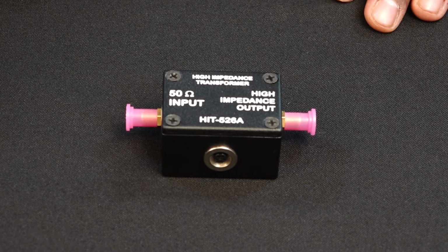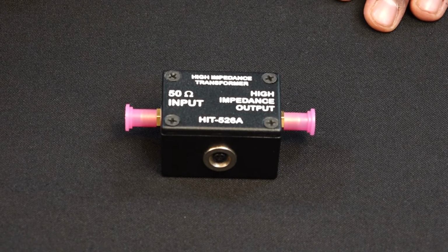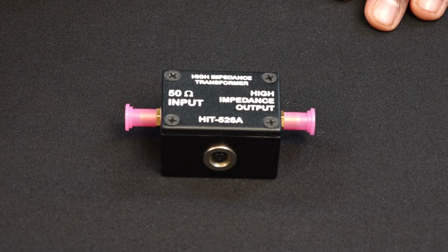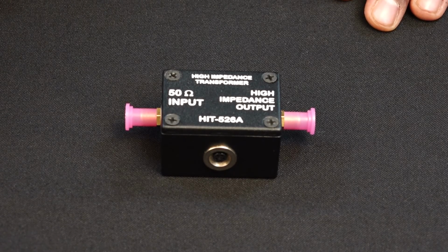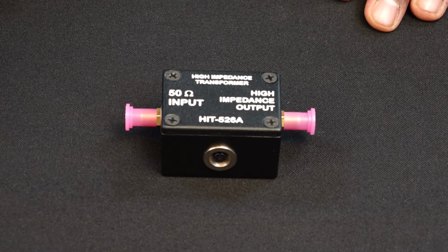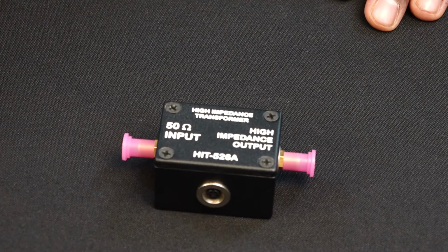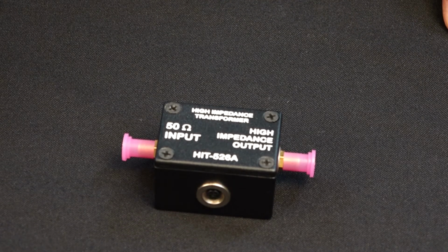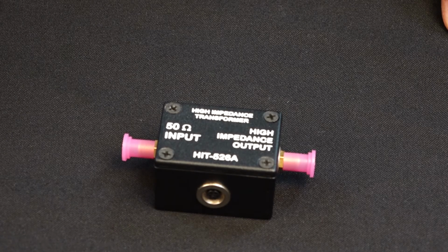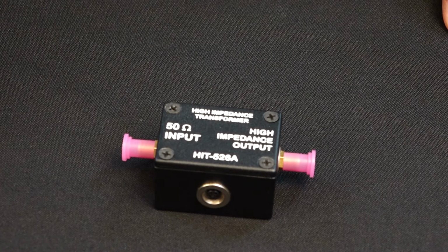The next component that I'm going to show you is called a high impedance transformer. I was telling you that all the transmission lines and all the components that we use have a 50 ohm characteristic impedance. Sometimes you would want the whole TLP setup to have a higher impedance than 50 ohms. In that case, these high impedance transformers come into play. You connect these high impedance transformers immediately after the switch that I've shown you before, and this transformer then switches the impedance of the whole setup from a 50 ohm setup to a 526 ohm setup. So you are then using a TLP transmission setup that has a characteristic impedance of 526 ohm.